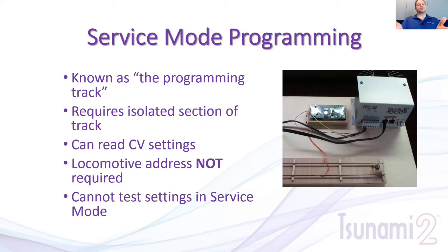Now the way it's actually yes and no is when the decoder answers no, nothing happens. So the DCC system then moves on to the next question. When the decoder answers yes, it will draw a surge in current internally or through the motor circuit. And that's when this isolated piece of track pays off, because we don't have anything else that's going to draw a current and surge. So the DCC system can say, I am getting that acknowledgement from the decoder I'm intending, so therefore that is the correct answer. Once the DCC system detects that surge in current, it says, I've got the answer, I'm good to go, and displays it in our window. So that's why when you go to read a CV value, you notice that if the value is higher, say a value of 220 or something like that, it takes a lot longer for that answer to come through, because it's asked 221 questions before it got to that.